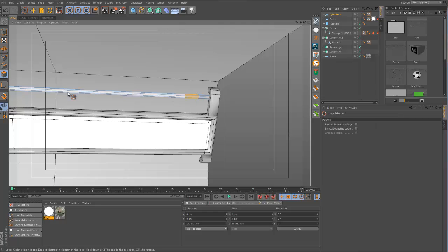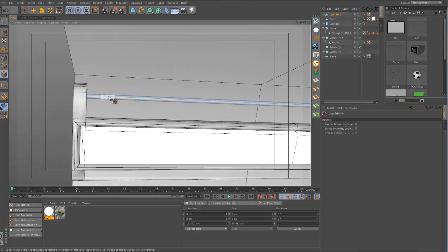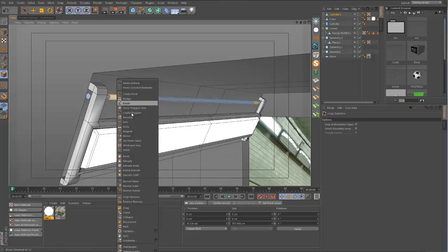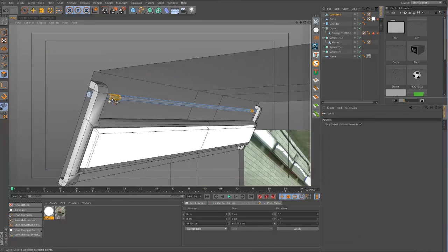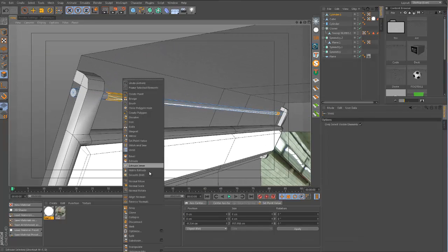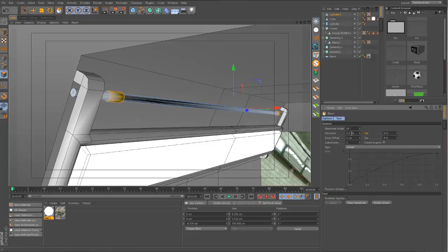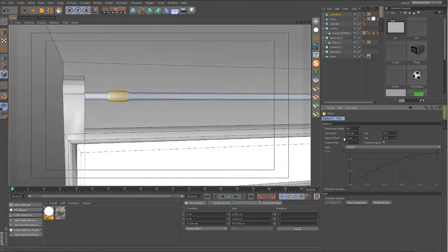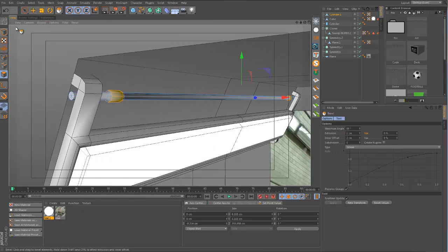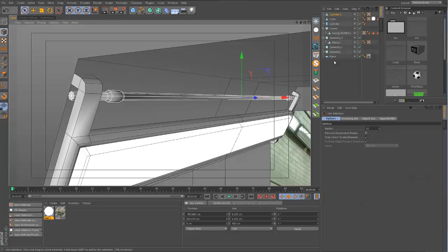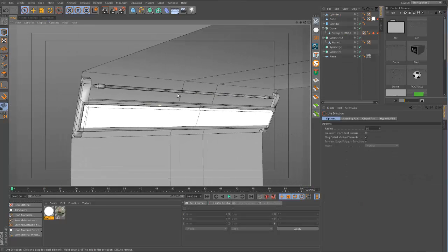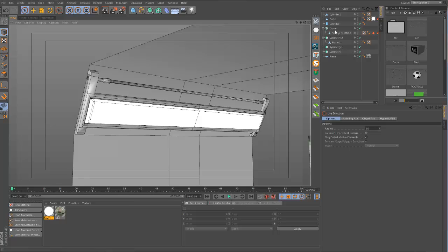Let's get loop selection. I'm just going to bevel this a little bit. Let's have an inner offset of 1, so it's nice and slanted, or maybe even 2. And an extrusion of 1. So we have this sort of pipe-like looking thing.